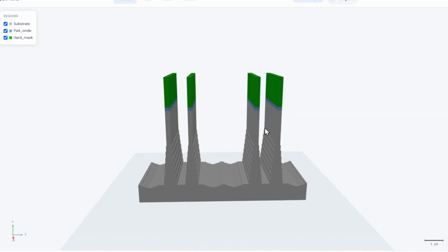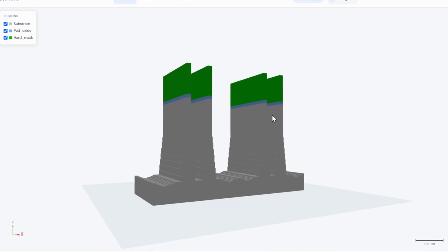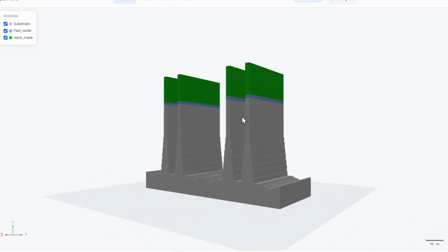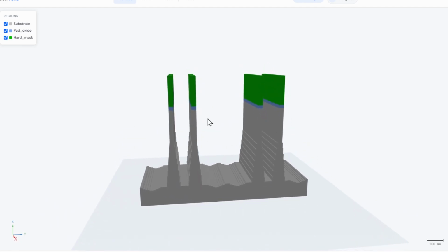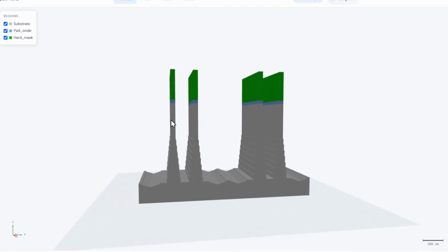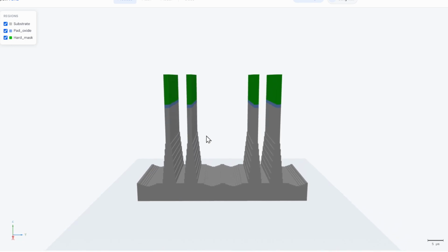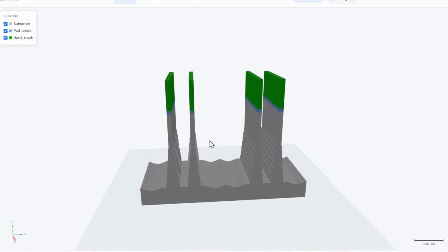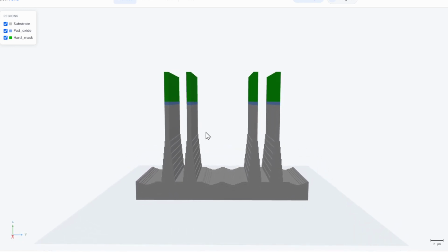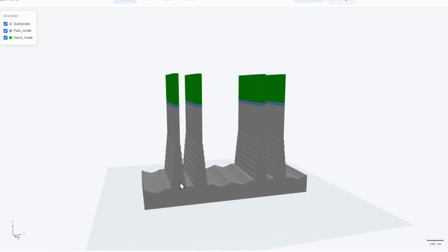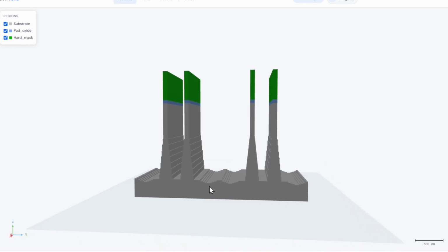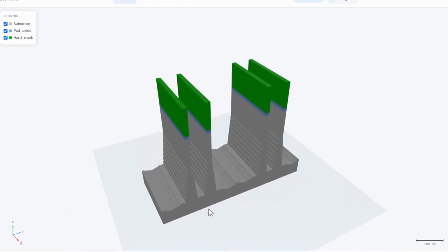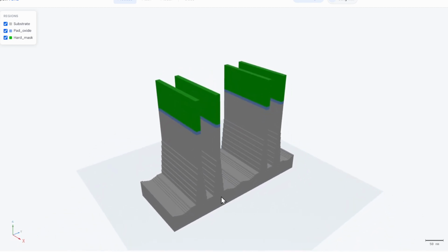Then by removing the silicon dioxide, we have only silicon fins. Yes, they look really beautiful, and we have fins whose thickness is about 7 nanometers, which originates from the deposition thickness of this layer, and they are placed in the positions where we wanted active regions. And for others, we don't have any fins. Yes, that's what we wanted to have.